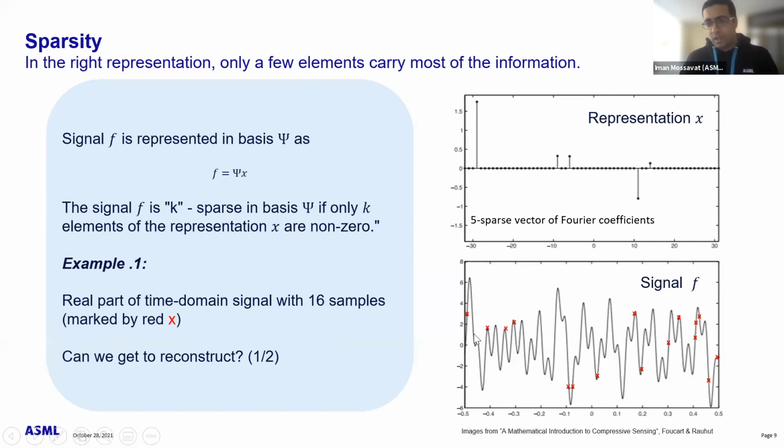And now I'm going to sample this signal F in an irregular grid and much lower than what we call the Nyquist rate. So in signal processing, there's a dogma: you have to sample as fast as or twice as fast as the highest frequency. And here you actually go below that. You kind of measure less and measure in an irregular grid, which is these red dots here. These are the measurement points of your signal.